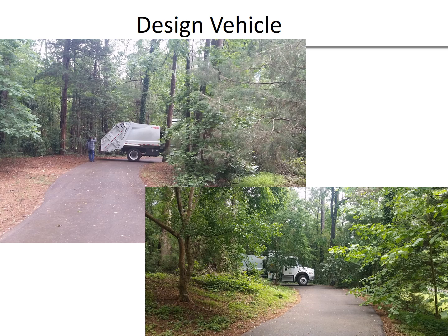And when you have these large vehicles that rarely turn at an intersection with moderate to high opposing traffic volumes, such as emergency vehicles, that could be another case where you consider them a control vehicle instead of a design vehicle. Again, the design vehicle is a vehicle that must regularly be accommodated without encroachment into the opposing traffic lanes. This is when you have large vehicles that are going to regularly turn in an intersection with high volumes of opposing traffic. And that may be a bus route. So if you're on a roadway with bus routes, you're probably going to need to have those buses incorporated as a design vehicle and not a control vehicle.